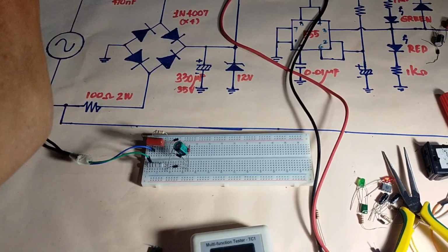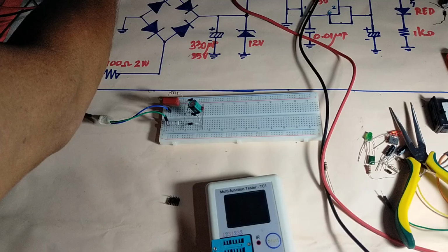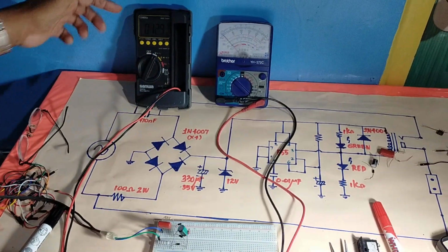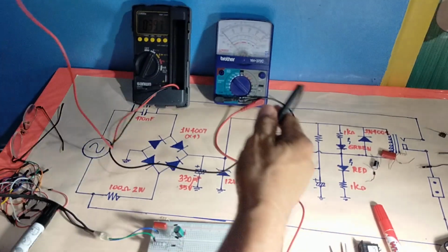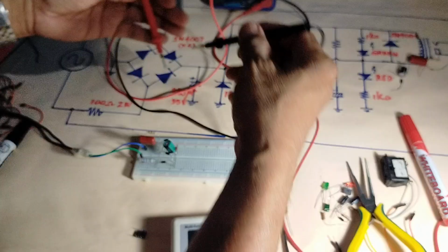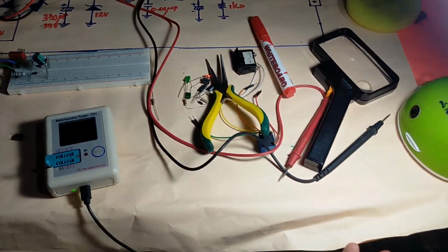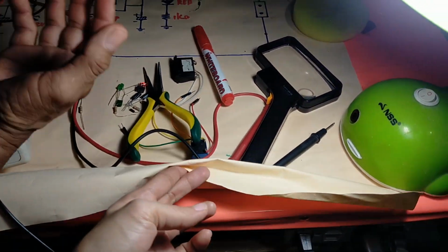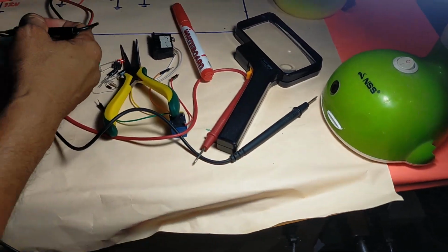So, let us measure the voltage here. Set it to voltmeter. Then DC. We are now at the DC voltmeter because the output voltage actually is no longer AC, although the voltage at the outlet is AC. But after rectification and regulation of the circuits, it is made DC.